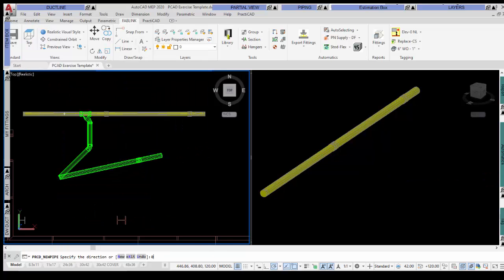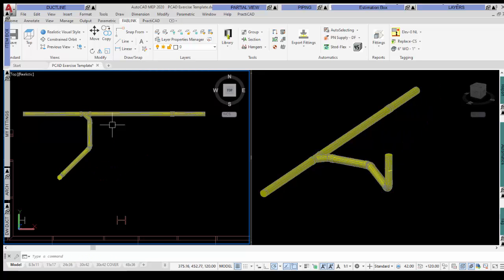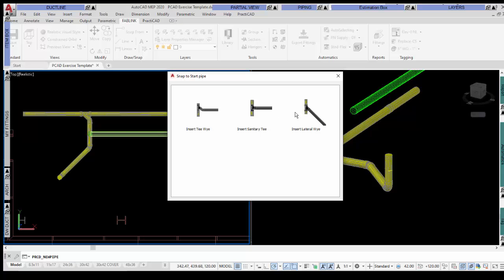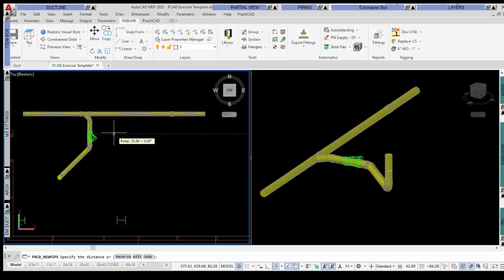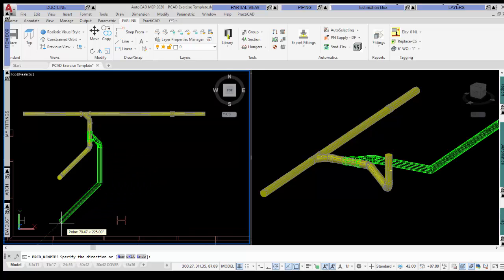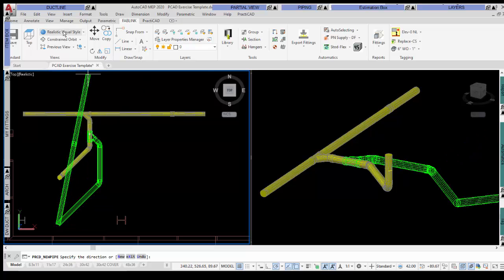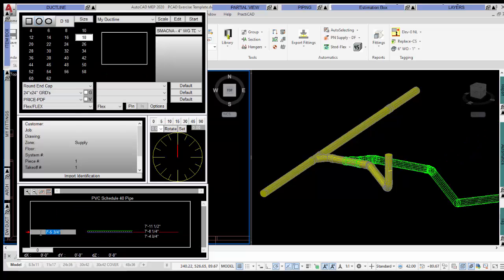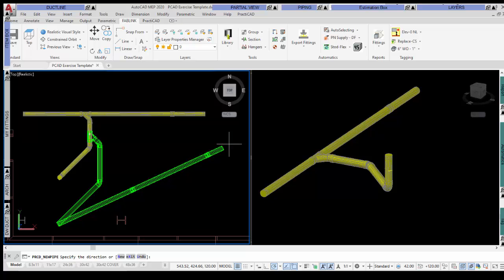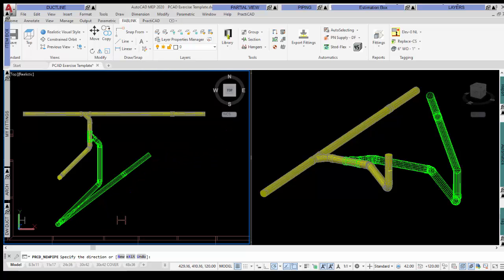If you watch carefully, you can see every elbow is automatically being generated on turns and elevation changes. Choices for tees are appearing in our routing box and seamlessly added into the line. Essentially, every mouse click you make refers back to your piping system components to choose whatever you allowed it to use, so you are in complete control of everything your auto pipeline does. Automating the selection of your components is a great time saver.